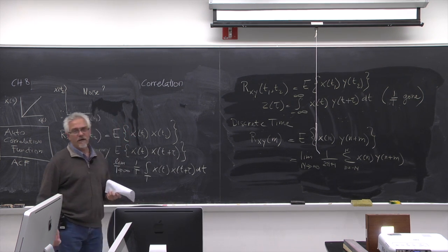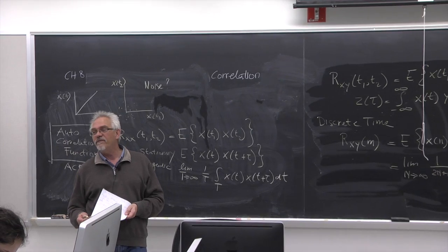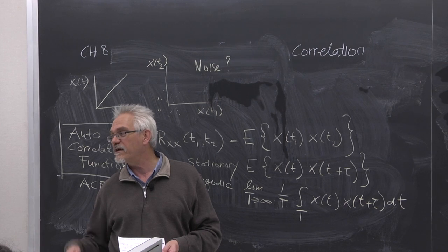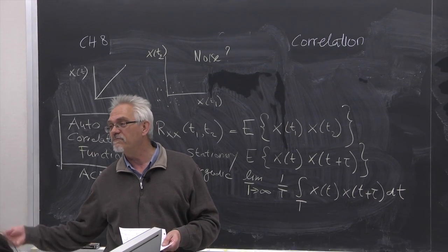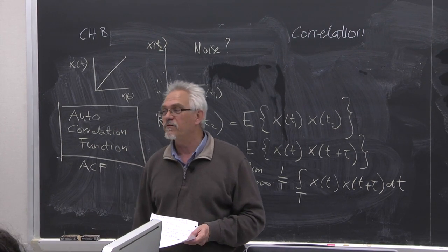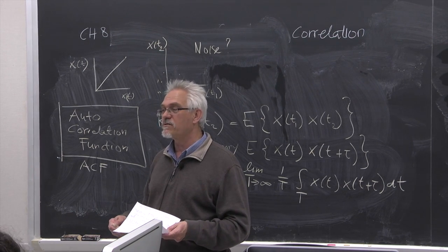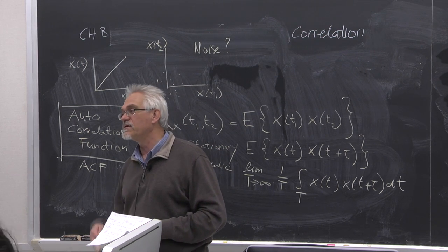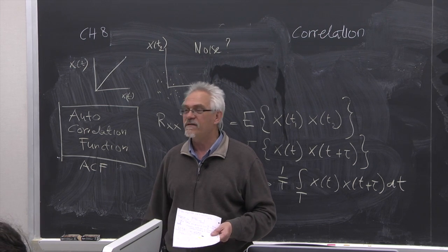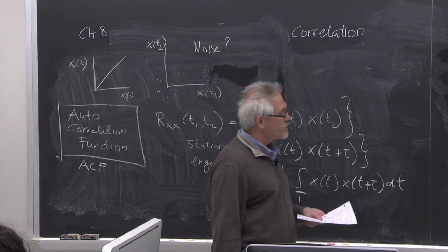In addition to cross correlation, we sometimes talk about cross covariance. And just as you have the moment and the central moment, the cross covariance is the cross correlation where the signals are demeaned prior to. So there's a little difference. Actually, I would recommend that whenever you look at cross correlations or autocorrelations, that you demean your signals, unless you have a special reason not to. Because your DC component in your signal, certainly in neuroscience, usually doesn't mean a whole lot. Except when you're looking at resting potentials, of course, then it's important. But in general, it's not too important.